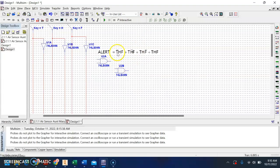First thing we're going to multiply together is not T and H. Not T is this one, after the inverter. Positive H is this one. Those two then have to get multiplied by positive F, which I think is this one. Then we repeat the process for T, not H, positive F.